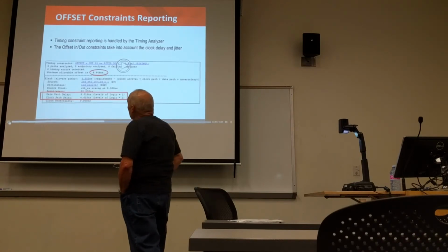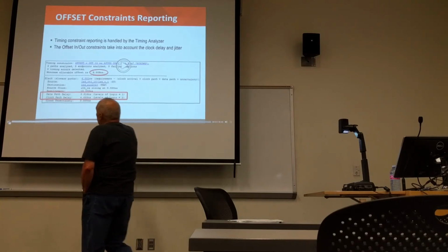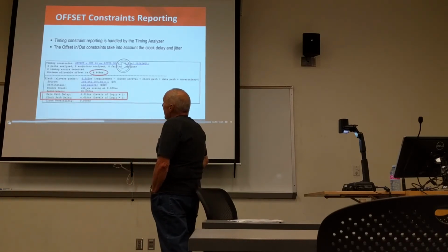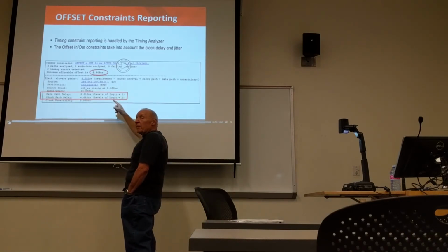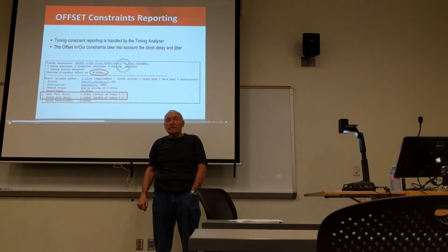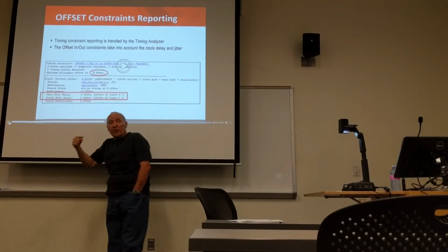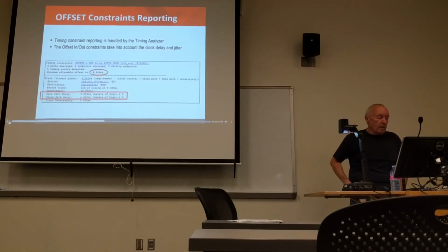That's your timing constraint. And in this particular path, it found a data path delay of something over 3 nanoseconds, and it found a clock path delay of over 4.6 nanoseconds. It also tells you here the levels of logic. Each time you have to go through a LUT, you've gone through one level of logic. So in the case of the clock delay, they went through 2 LUTs to get to the device. From synchronous elements to output pins.